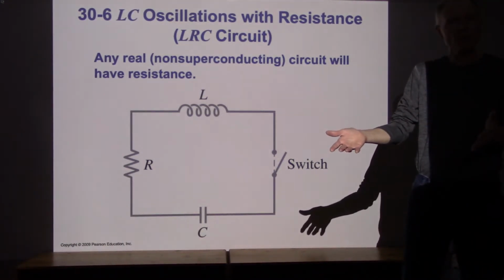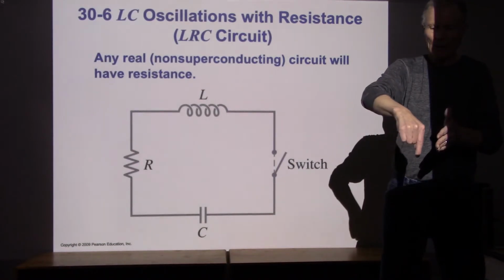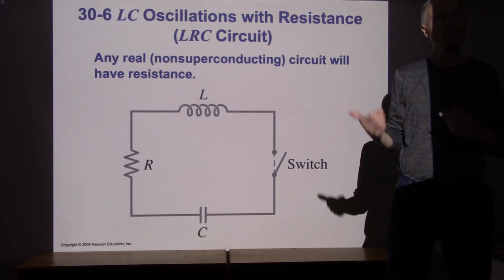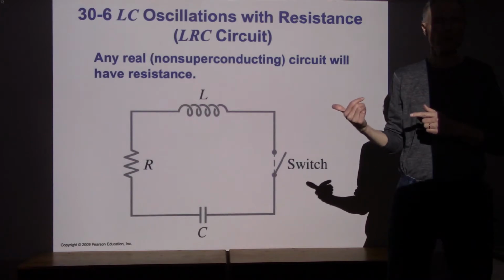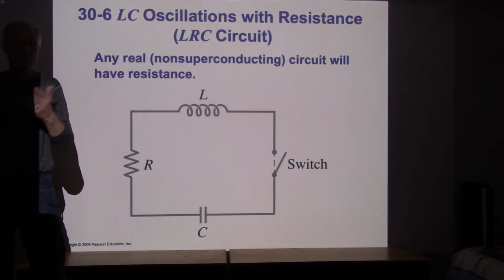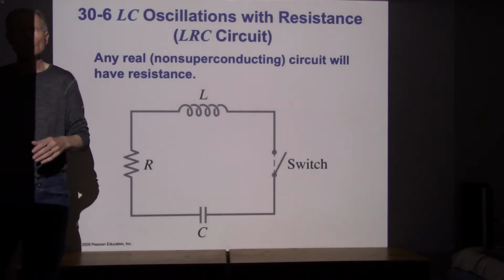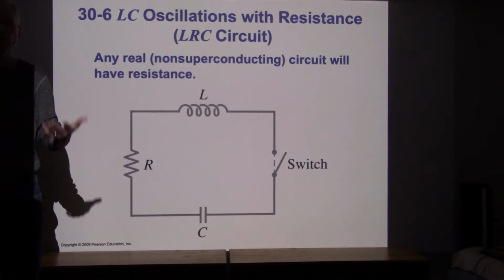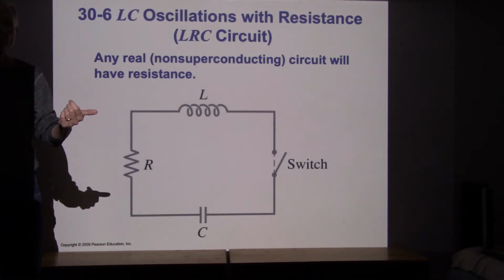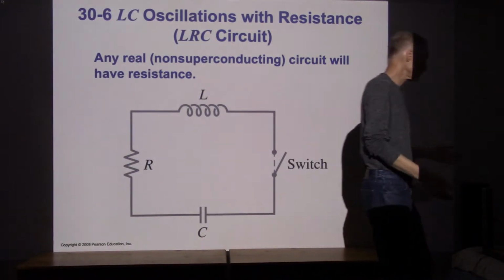Once we cross a certain threshold, I let go of the pendulum, there is now so much resistance that it slows down and it never crosses the equilibrium position. That's what happens when we put enough resistance into this circuit. So if I stay below the threshold, I'll get those oscillations. The oscillations will be dying off. But if I put more resistance in, then the circuit will use up all of its energy in just returning to equilibrium. So those are predictions, again, from the mathematics. We can go into the lab and verify that's really what happens for different values of resistance.